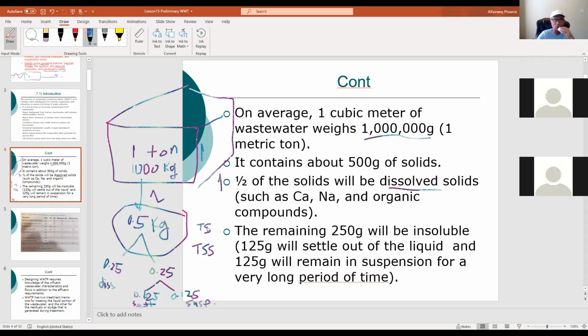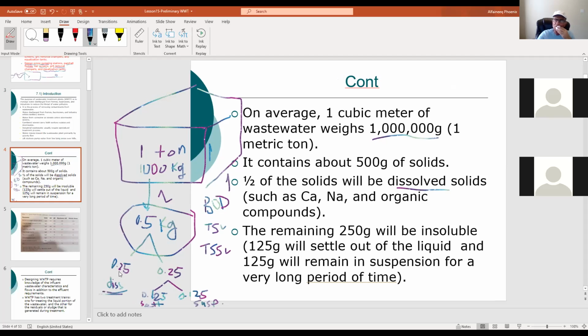But these are the two most important factors. BOD, right? BOD soluble, here, part of it is organic in this part. Nitrogen compounds, phosphorus compounds. These characteristics of the wastewater tell you how strong it is, the strength of it. This number, mainly BOD.